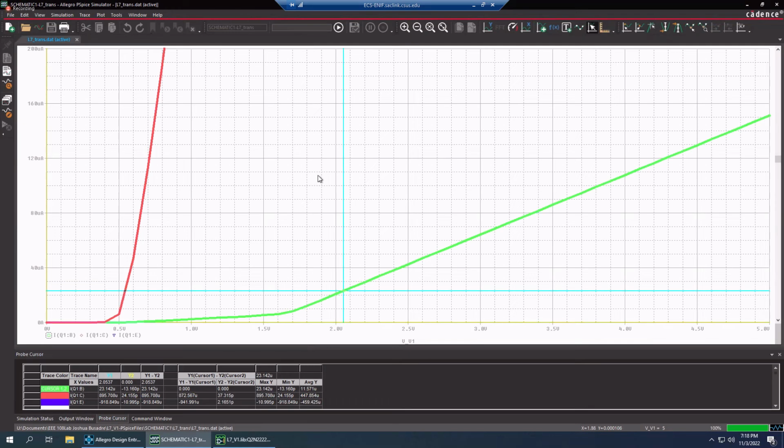Interesting. You can see where we don't see the saturation on the red curve, but you can see the knee of the curve, when the transistor is fully turned on, and then you're putting a lot of current in there, but you're really not changing the voltage. The collector is basically going to be pulled down to the emitter. Anyway, that was just for my amusement. You don't necessarily have to put that in your lab report unless you want to.